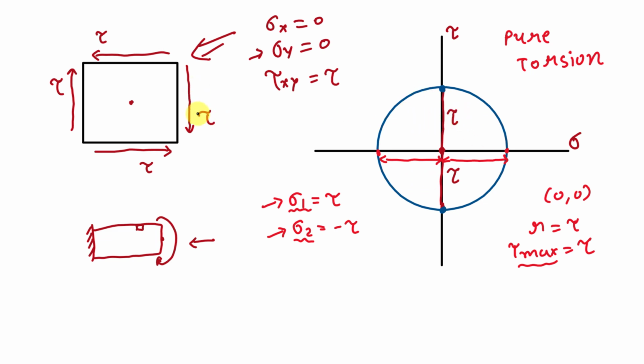If there is shear stress and normal stress acting simultaneously on the body, then we can use the equations discussed in the previous video, because in that case it will be easy to find these values by using equations rather than the Mohr circle. Fine. So you can find these values by using the Mohr circle in this type of easy cases. But if complex loading is given, then you can use the equations that we have discussed earlier.